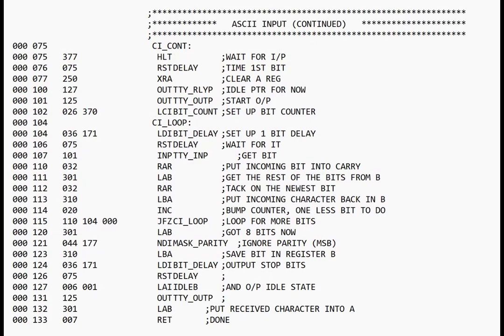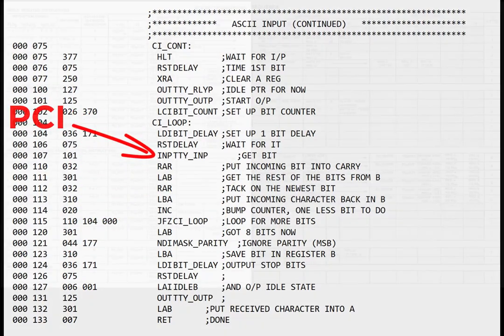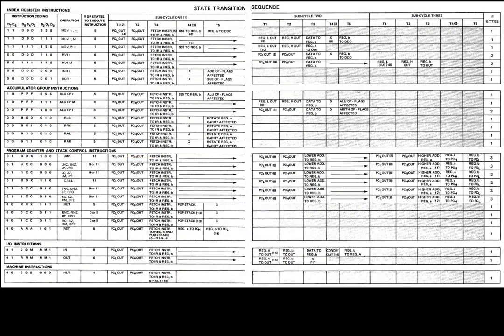Again, it's critical that when it interprets the instruction in the PCI, the 8008 needs to determine if there are going to be more subcycles needed to complete that instruction. Maybe, for example, it's just done with the PCI and the next subcycle is just another PCI. Of the 27 instruction types, not quite half of them, 13 of them, are completed with just the first PCI.